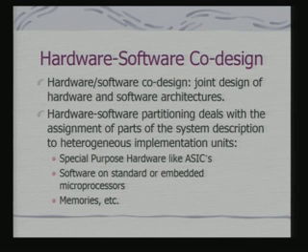Those parts of the tasks which get mapped onto the hardware get mapped onto ASICs or any other special purpose hardware. Also, we would look at the memory and other requirements through this process. So, the key issue for an embedded system design is this hardware-software co-design, which implies hardware-software partitioning.